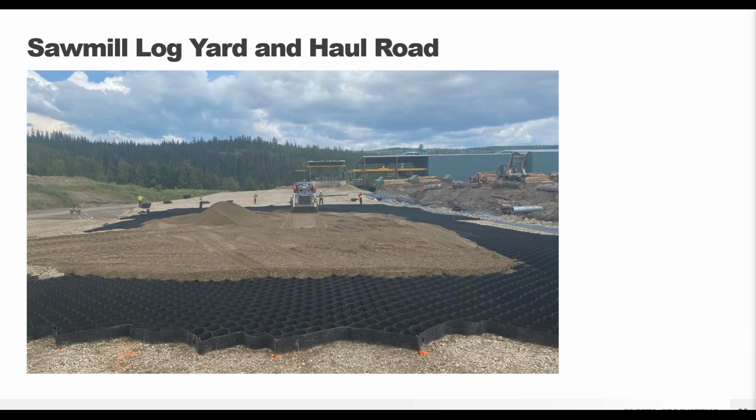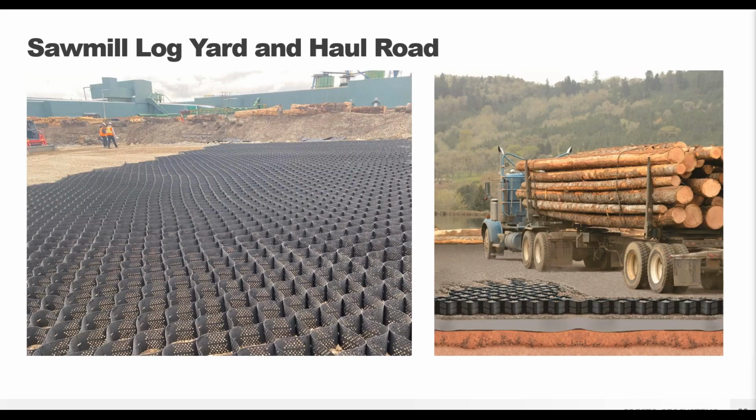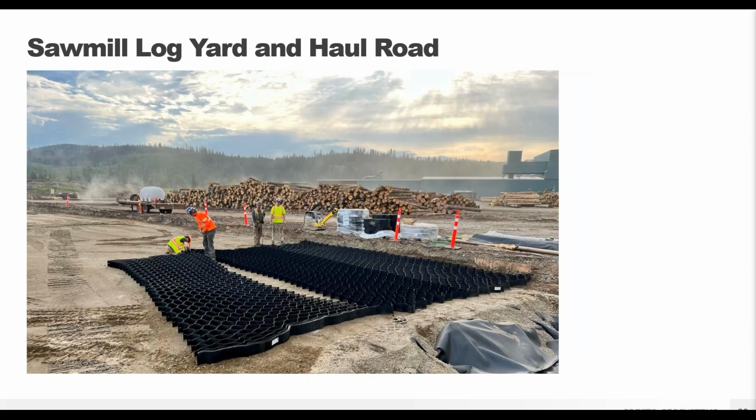So this was a project for a sawmill in British Columbia up in Canada. Spring snowmelt and fall rains typically were causing flooding in this area, creating soft, challenging soil conditions for the infeed area for the mill. So Presto worked with the owners to develop a design to manage both stormwater and snowmelt while providing stabilization and support of the heavy loads over a soft subgrade. In this case, they chose to use a 6-inch deep GeoWeb load support system, and they included a high-strength woven geotextile that was designed to help promote stormwater infiltration.